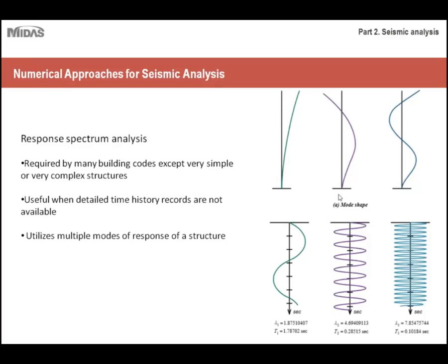For example, if you're only designed for this mode or only designed for this mode, and you neglect these previous two, you'd essentially be designing your building to withstand one portion of the earthquake but not the other. So that's why taking all of these modes is very important, just to take into account critical loading conditions for various points of the earthquake.